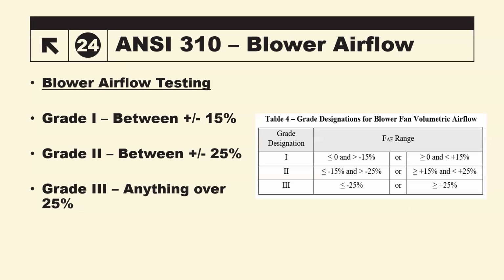If it can't push it out because of crushed ductwork, or if it can't return that amount of airflow back to the system, whatever's coming in the back end is going to go out the front end. So it's not going to magically push more air. In other words, if it's 1600 CFM I'm needing and I only get 1450, it's not now going to push 1600 in front of it, and now, well, we're still getting 16 on the supply, but only 14.